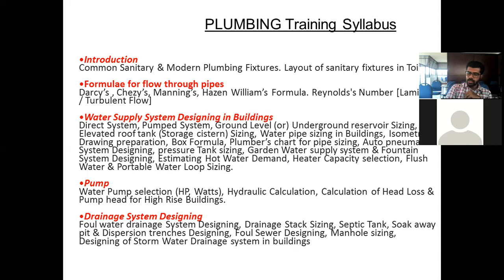For the water supply, there won't be any change in the main supply pipe dimensions. You can choose when you buy a pump and motor. The outlet and the inlet pipe diameters will be mentioned there: 25 to 25, 25 to 32, 32 to 32 mm.